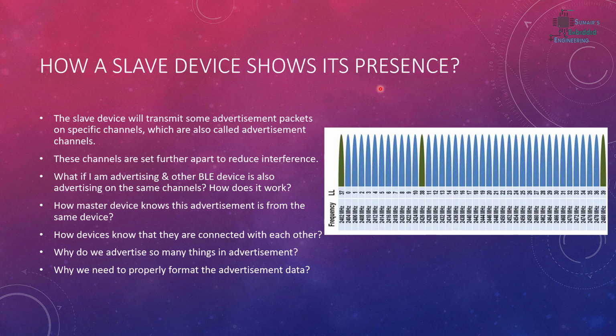Basically we are just setting these values so that our advertisement lasts just a couple of milliseconds, and then the advertisement will not be on the same channel anymore. So for all of the other time, the channel is open, and it's easy for other devices to start advertising, even if we have so many devices there. If the advertisement is just for a couple of milliseconds, it's not a big deal for other devices to keep on advertising during the same time, because we have 3 different channels for that.